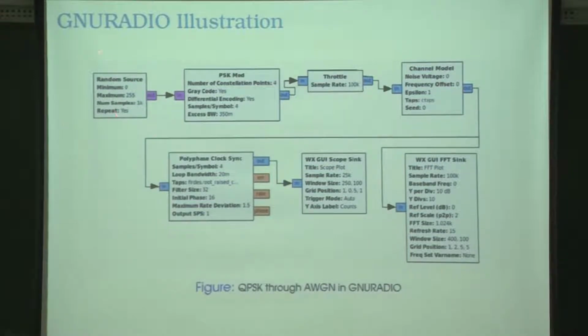So what we have is a source, and we send it through a modulation here, right? For the computer science people, the modulation may be new. Is it new? Yeah, okay. So what we are doing is taking these messages and converting them to symbols which I can push through the system. In particular, I am using what is known as PSK or QPSK, where I take two bits and send out a complex value.